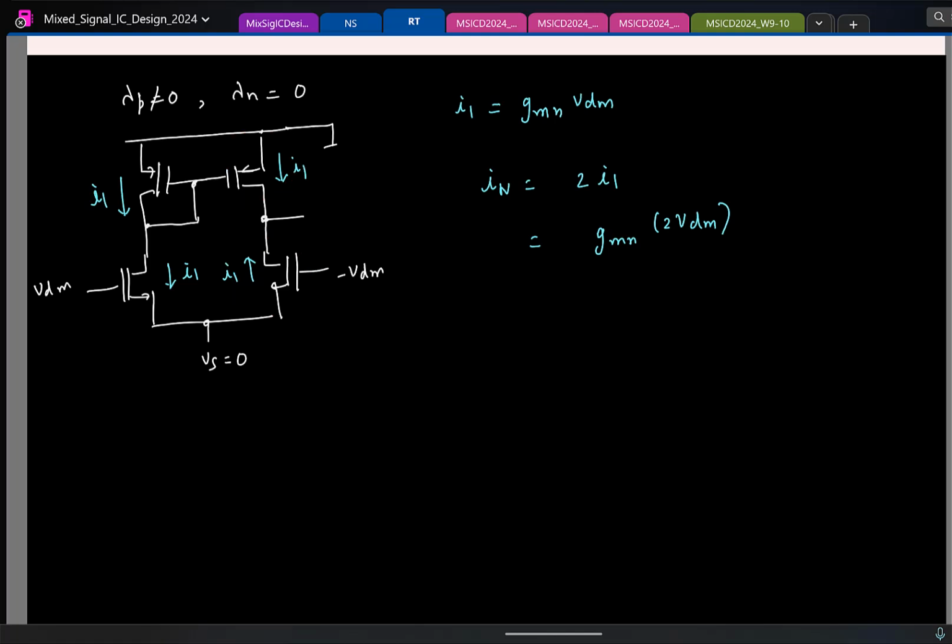What we have assumed is NMOS has no lambda. So any change you make at this point will result in 0 current here. So this is as though it's open with respect to the impedance calculation. So I only have the PMOS, and what is the effective resistance looking into the drain of the PMOS transistor? RDS of the PMOS transistor.